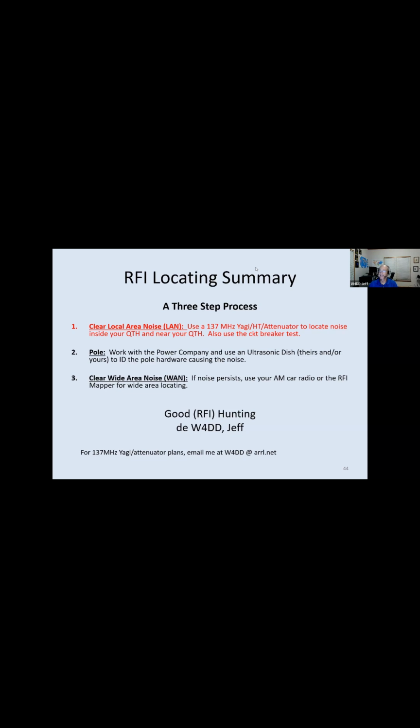Anyway, he understood right off the bat what was going on. They sent a tech out. Like you said, we had isolated it down to the poles, we think maybe 2 or 3 poles. Net end result, PG&E did come out. They shut off power to 409 people and replaced insulators on 3 poles, crossbars, joints, and the top insulator. Those were 7 kV lines, 2 of them. And that brought the noise down to about S5.